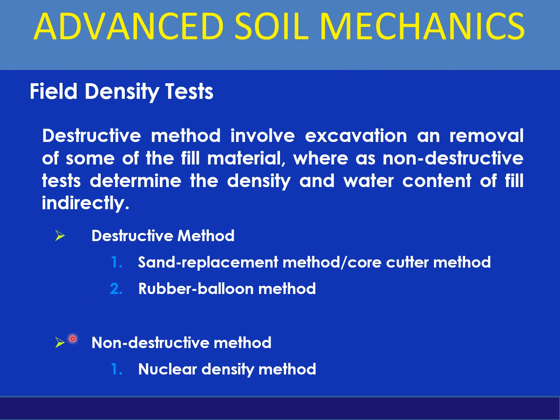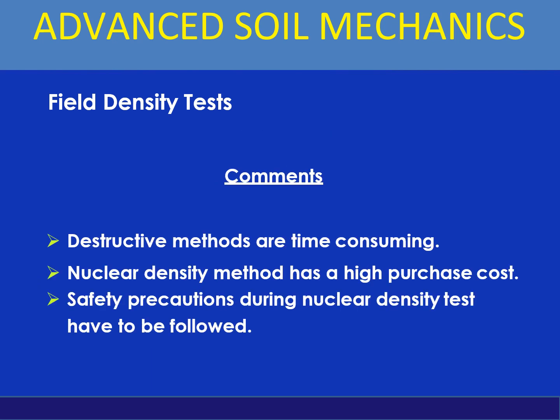In non-destructive methods, we use the nuclear density method. Field density tests by destructive methods are time consuming. The nuclear density method has a high purchase cost, that means the initial cost is high. Safety precautions during the nuclear density test have to be followed.